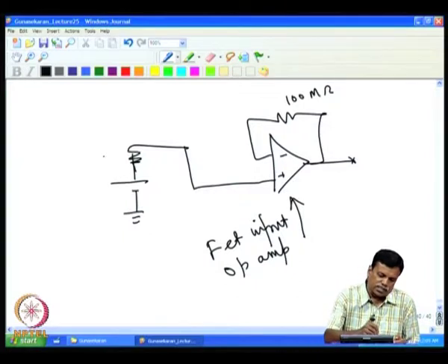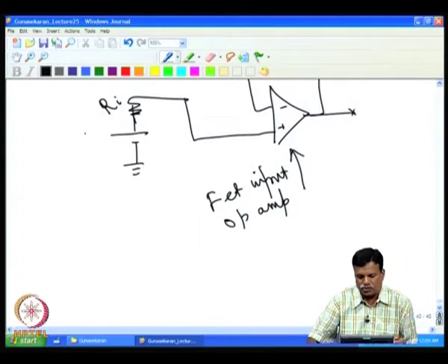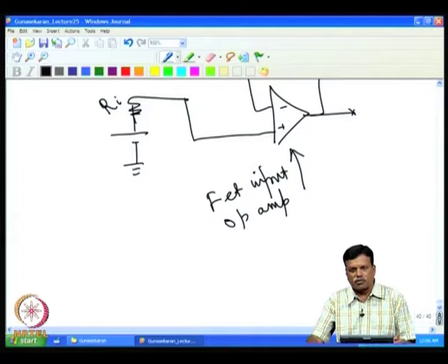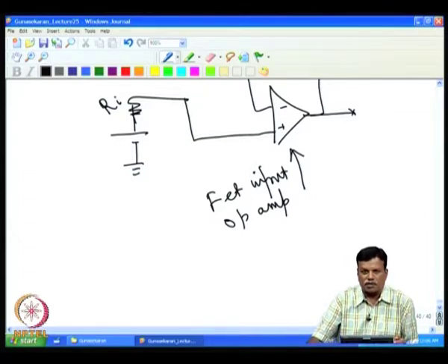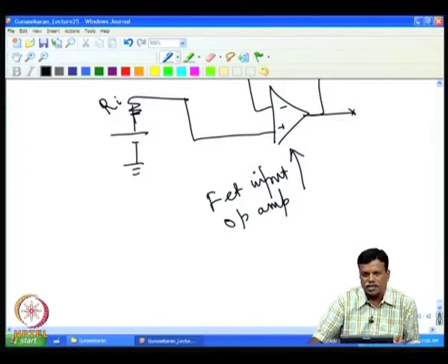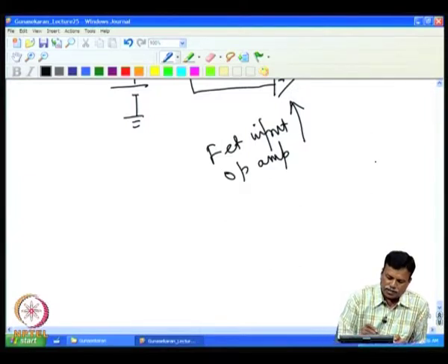Now we are discussing the error due to the offset current. Since we are at it, we also have to worry, when selecting a low bias current op amp and making a printed circuit board layout, about other current getting into the PCB, which is a much more serious problem than the offset current itself. Let us see what care we have to take when dealing with issues in low bias current op amps.